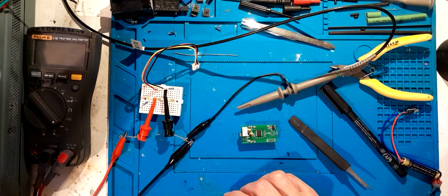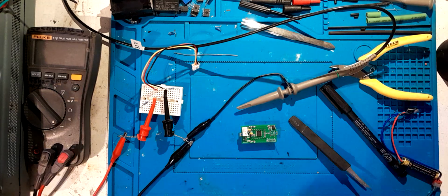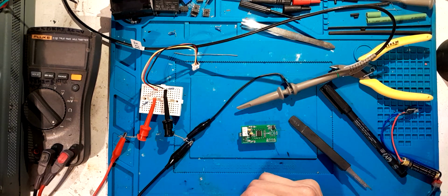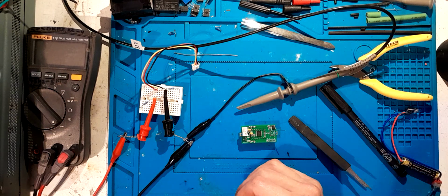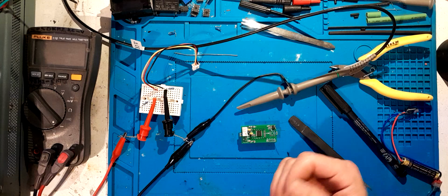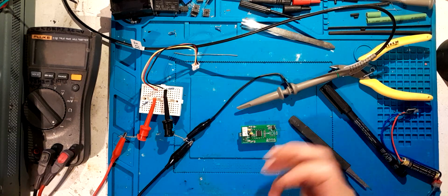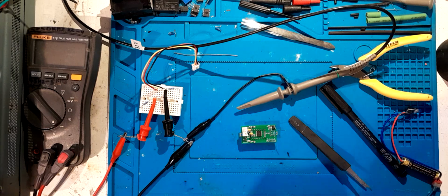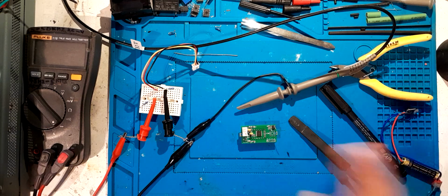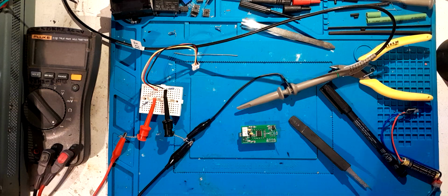I just wanted to point that out because, like the thing that I showed you with the series pass transistor not being able to have a reverse voltage on it, I thought I should point that out too, because it's just another trap for young players. You could design a circuit that's got a micro and an ADC in the micro and an external voltage reference, or an internal one, and some regulators around the board and op amps and different things, and have a few millivolts of ripple on there and be like, ah, that's only a few millivolts of ripple, that's fine.